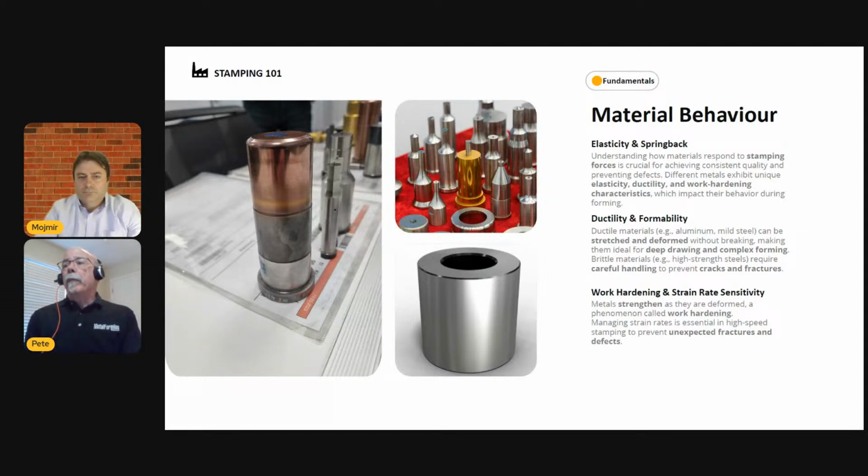Some people have said they would like a material that doesn't work harden. You may have heard that yourself. You may have even uttered those words. But something to think about: if the sheet metal did not work harden, you could not form it.